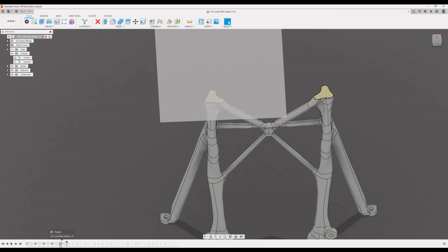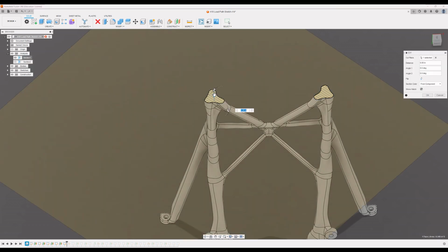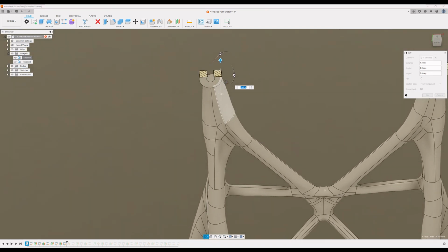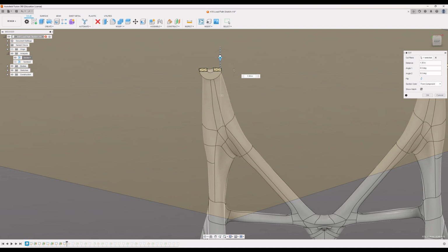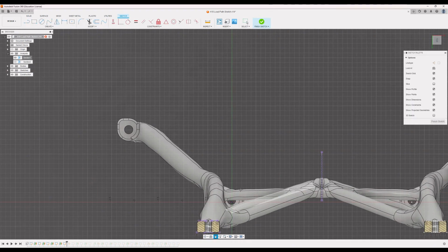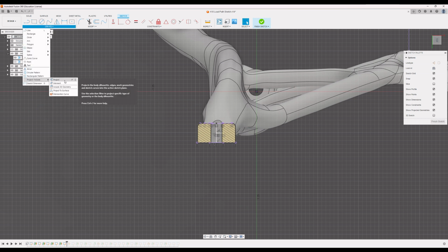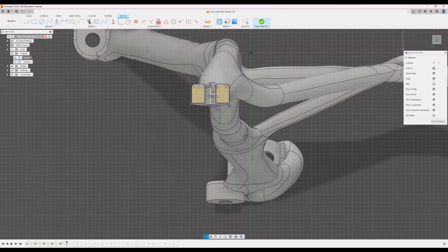The final point here is to move up and find that final bolt point. And again, it's important to get these in there because this is where the lines of force will originate or end. So in our case, this is a load, and this combined with the bottom one create the lines that actually permeate through the structure. And again, just like before, we'll go in and we'll use the project feature and we'll construct and find the center point for this bolt hole.